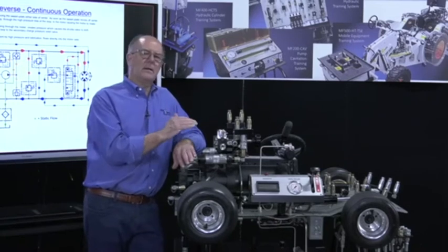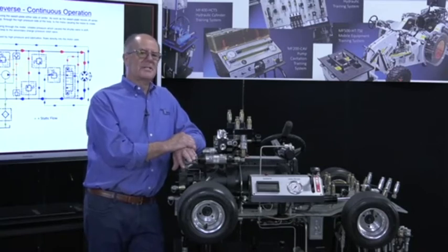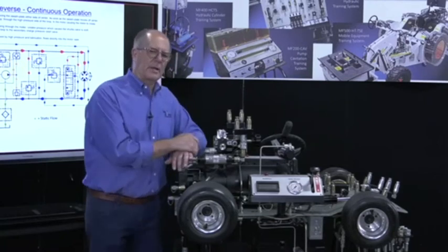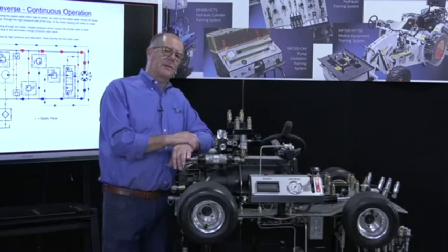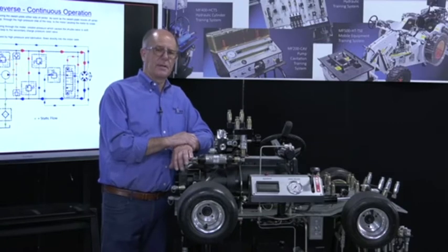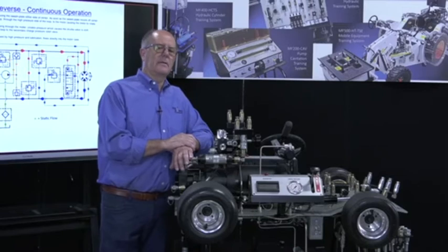I have been to machine after machine after machine where they started out with a catastrophic failure, and then they went through, in one particular instance, 7 pumps and 8 motors, but they could not restart. They kept repeating the failure. What they did out of desperation is they started putting high pressure filters in the loop, which is the worst thing you can possibly do. Because high pressure filters in a closed loop system serve no purpose. In fact, in my opinion, they create more problems.